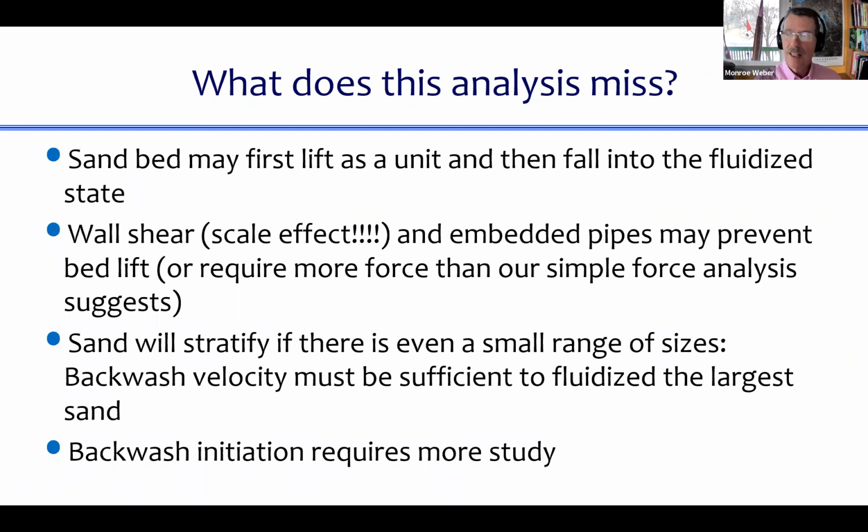And that matters because that means that in our filter system, where we have lots of pipes in the bed, initially you're going to put a lot of force on all those pipes, because you're trying to lift that whole sand bed, and the pipes that are in the bed are trying not to move. And so you'll apply a lot of force to those pipes right at that transition. And we have demonstrated this. We have broken things inside of filters because of not realizing how strong that force was.